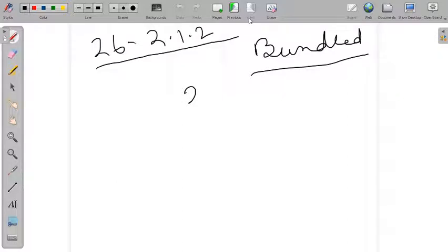The guidelines say that the development length of each bar of bundled bars shall be that of the individual bar, increased by 10% for 2 bars in contact, 20% for 3 bars in contact, and 33% for 4 bars in contact. That means when 2 bars are in contact together, the development length will be increased by 10%.